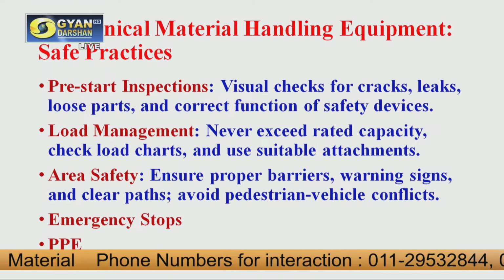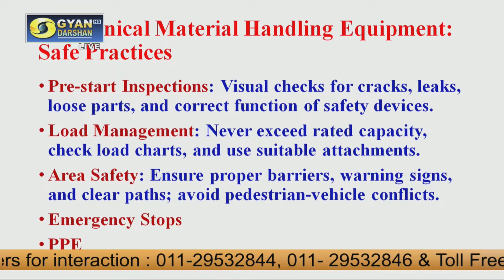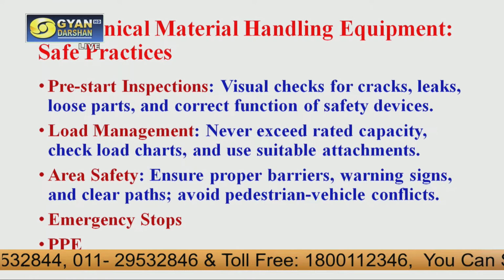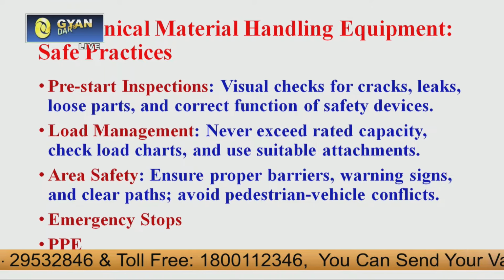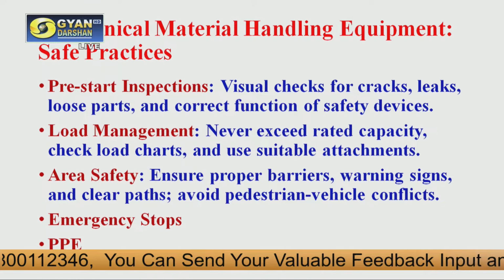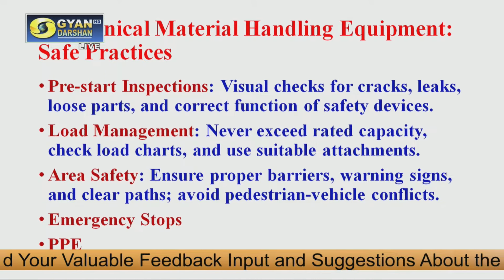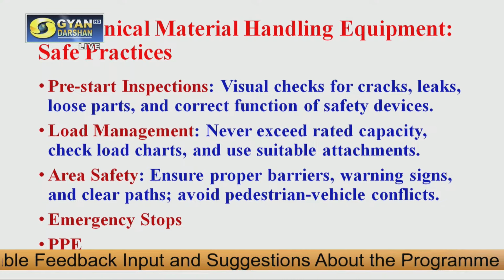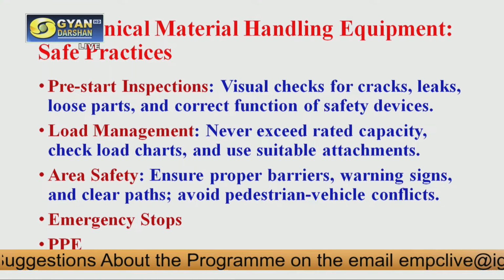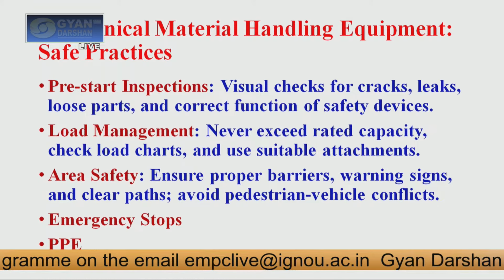So the first one is visual inspection for any crack or leakage. If it has a hydraulic system, there should not be any leakage in that hydraulic system, because if it is leaking, then the hydraulic system will not work basically. So that way we have to do the pre-start or pre-work inspection of our machines and equipment.